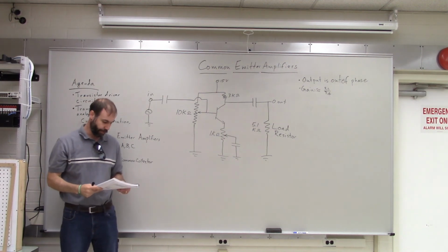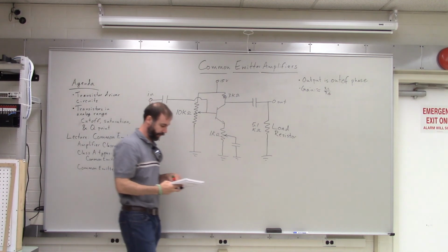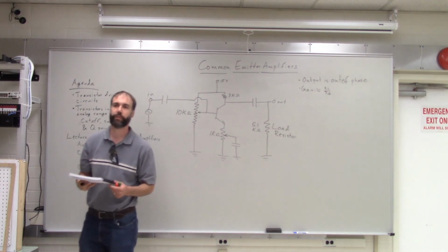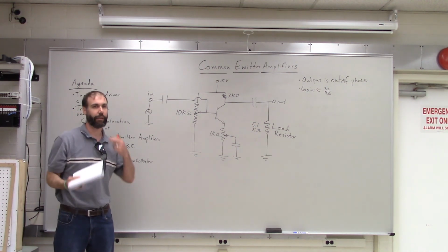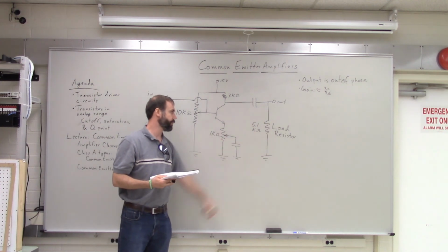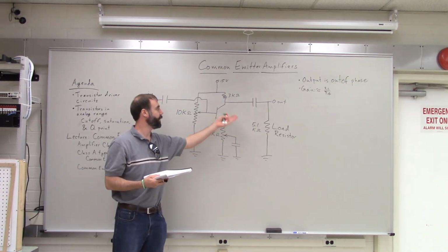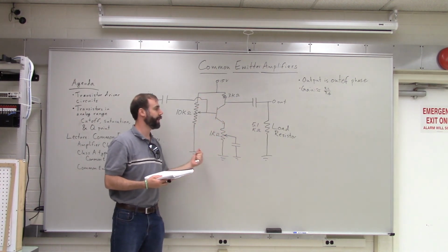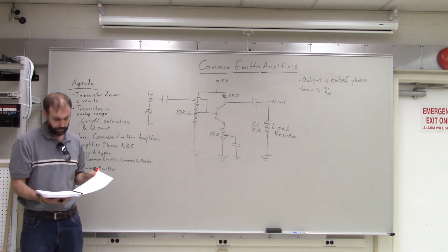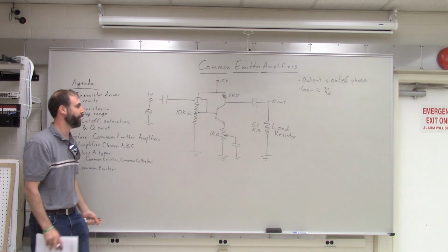So you're going to put in some smaller and smaller resistors, and the smallest one is going to be about 8 ohm. Any idea why we might choose 8 ohms? Speakers. Yeah, a lot of speakers are 8 ohms. So if you put an 8 ohm resistor there, you would see what the signal might look like if you tried to drive a speaker using this type of amplifier. All right. So that's what we're going to be doing in lab tonight.